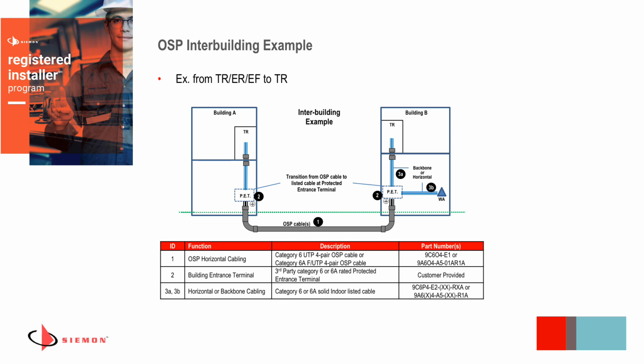In those instances, when that OSP cable enters the building, not only does it have to either transition or be installed in conduit, but it also has to have some primary protection, kind of building entrance protectors, if you will, to ensure that if there was a voltage surge or lightning on something on the outside, it can't transmit voltage. It's a primary protector when it enters into the facility. Those are installed by third parties, but it's absolutely required when you enter a cable into the building. So it's a little bit of a different application than within a building, but OSP cables between buildings are extremely common.